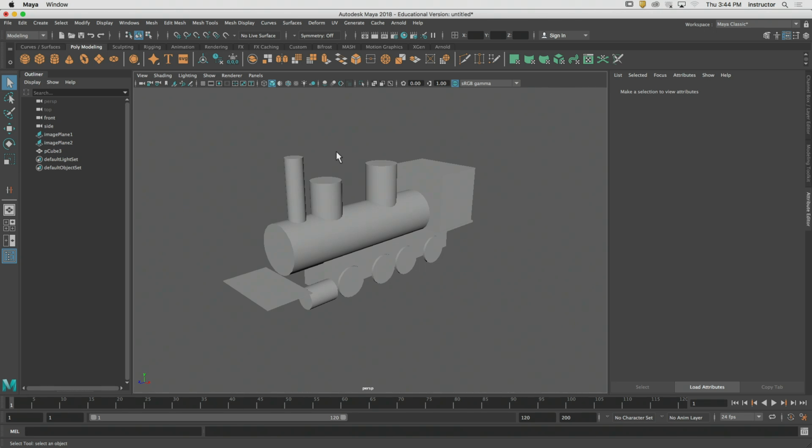This is, in every sense, the box modeling technique. We've talked a little bit about this in the past, but box modeling really is this. We start with a basic shape like a cylinder or a square, and then we start to slice and edit that cylinder or square into finer parts and pieces that represent different areas of the model itself, okay? This is the detail in method, okay? So we start with a big, broad brushstroke, and we go into the details. There are other modeling techniques, like a loop modeling technique, where it's the opposite. It's detail out.